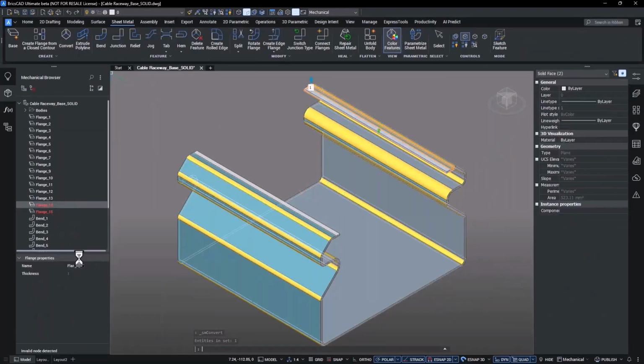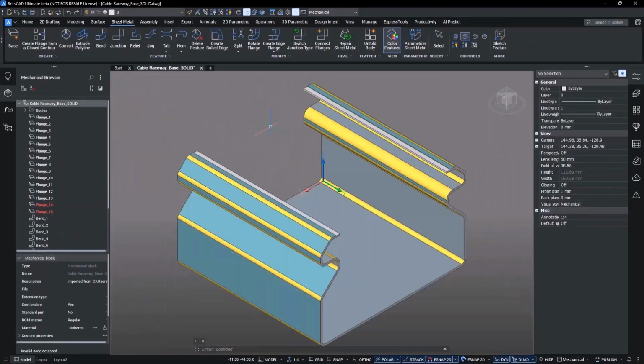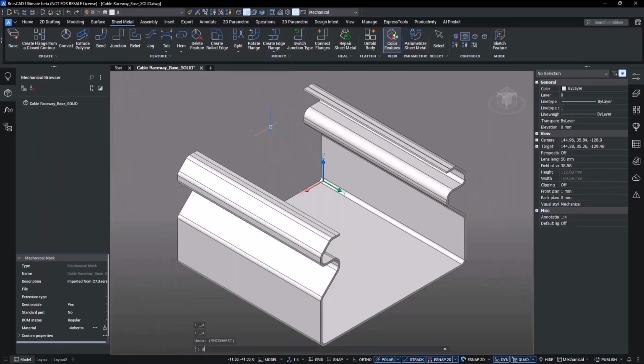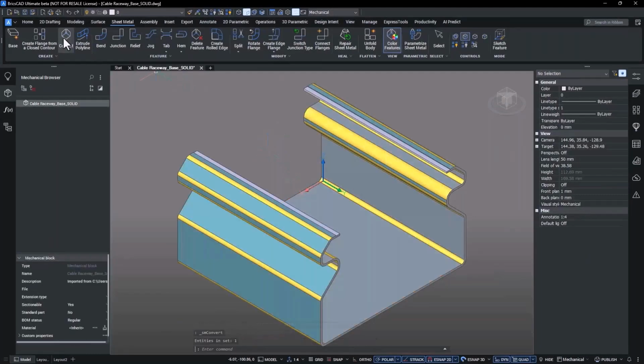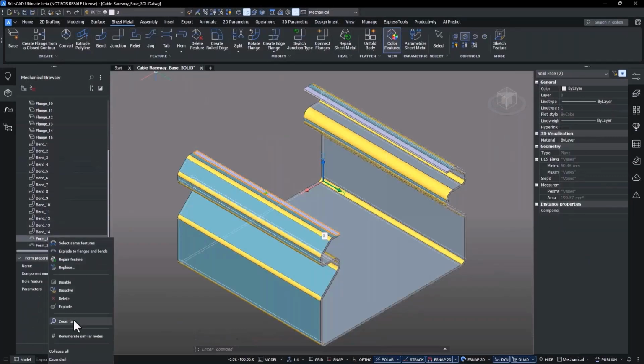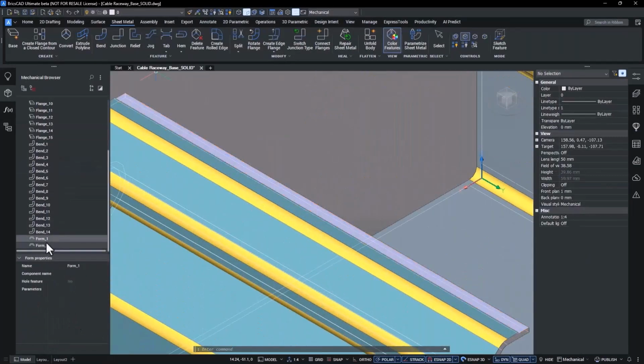Notice this form feature at the edge isn't recognized. To fix this, we'll adjust a new setting, SM convert maximal extrusion depth near border. This controls how far a form feature can extend near borders and still be classified. Now, we'll rerun SM convert, and the edge touching form is now correctly recognized, ready for unfold and manufacture.